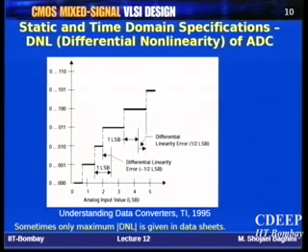This means that, as you can see, your step sizes or segment sizes are not the same anymore. That leads to nonlinearity, because if you connect these middle points together, you now get a curve. It's not a line anymore. Your characteristic now shows a distorted characteristic. It's not a perfect line. That's why it is called differential: you are comparing the difference between the transition points of two consecutive threshold values. Sometimes in data sheets, you may notice they give only the maximum absolute value of DNL, because after all, that gives you the worst case value.